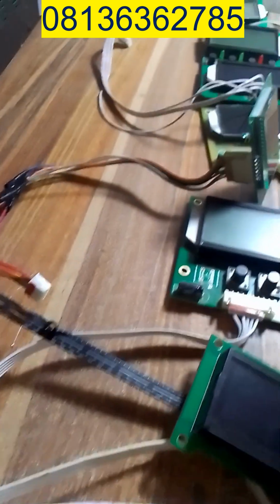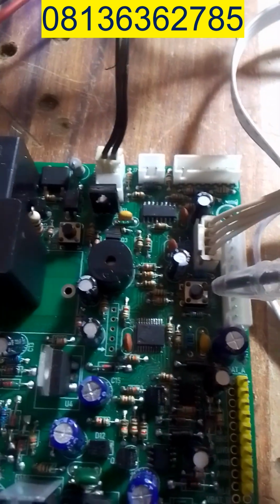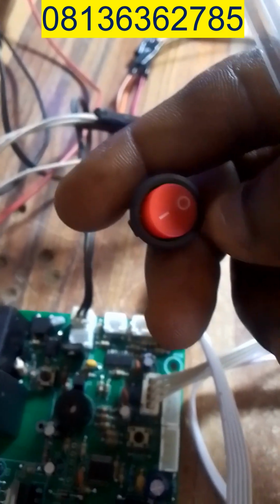So it depends on how you set it during the diagnostic mode. If you press this button down, this other one, during the time you want to change the LCD by pressing this one, it means you are using this display to switch the inverter on and off. But if you didn't press this button, you didn't hold it down while you are changing the LCD, it means you are working with this type of switch. Are you with me now?